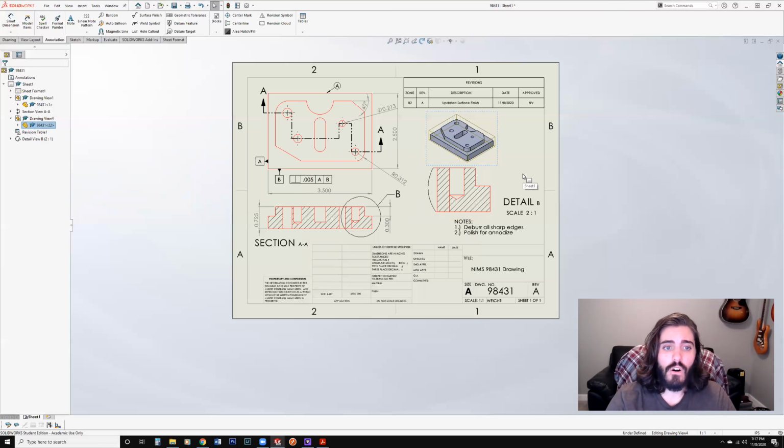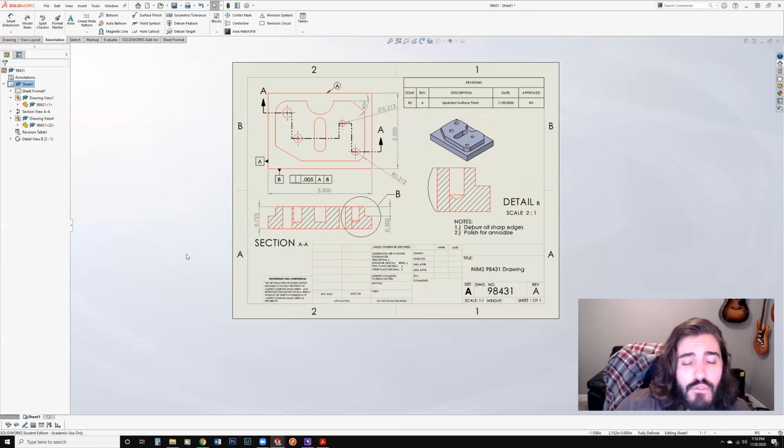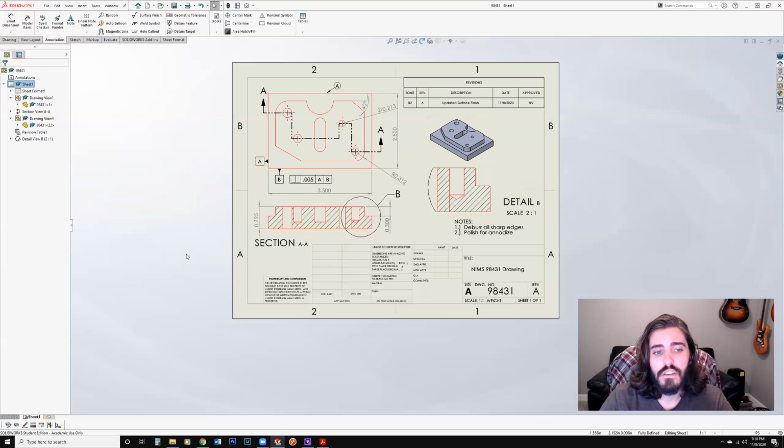So you're going to see that all of my parts inside of my drawing here that were associated to this part level and that layer are going to update with the red color that we created, which is really helpful because I'm going to save this again. If I ever want to import this from a reverse engineering standpoint, somebody can either turn off or turn on layers, and it's going to be really advantageous for somebody if they want to just remove all of the dimensions and they just want the drawing itself, and I'll show you why.